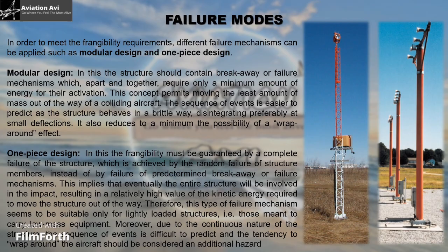One-piece design. In this, the frangibility must be guaranteed by a complete failure of the structure, which is achieved by the random failure of the structure members instead of by failure of a predetermined breakaway mechanism. This implies that eventually the entire structure will be involved in the impact, resulting in a relatively high value of kinetic energy required to move the structure out of the way.